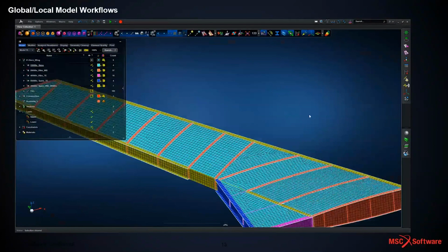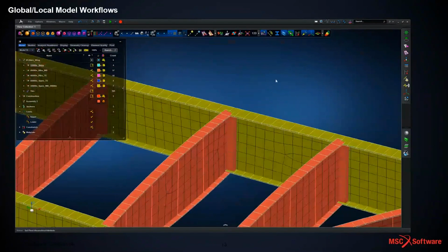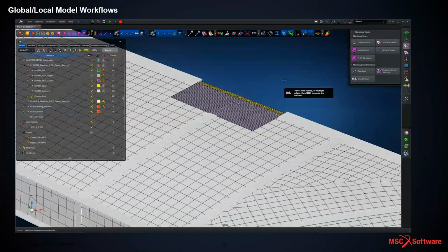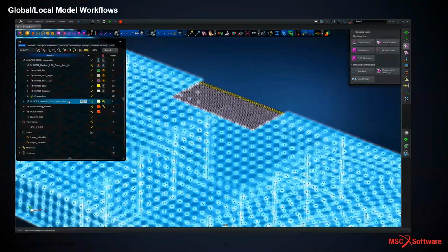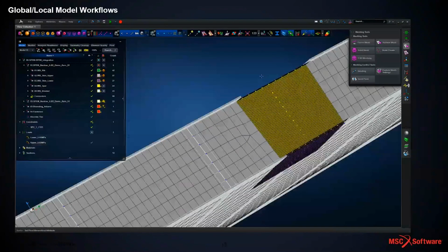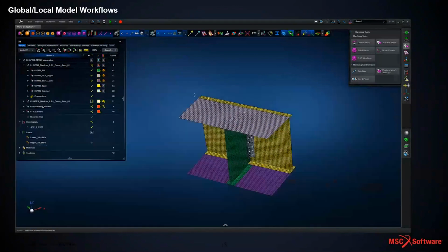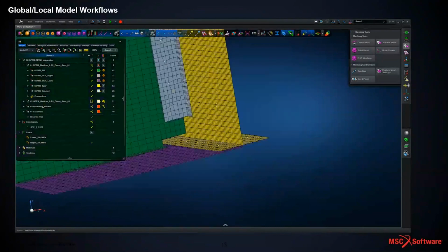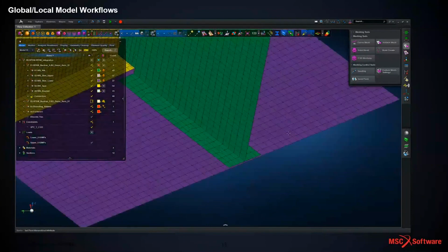So looking back at this demo, we've got some Wingbox topology, and we zoom in and show that's the topology that we've started off with. So using some of the orthomesh workflows that we've looked at in the previous demo, we've created our faceted surfaces, remeshed, and modified that geometry to suit the local geometry that we may wish to address. Of course, we could couple that with bringing in underlying CAD data, which we have done for a bracket, an interface bracket between the spar and wing rib.